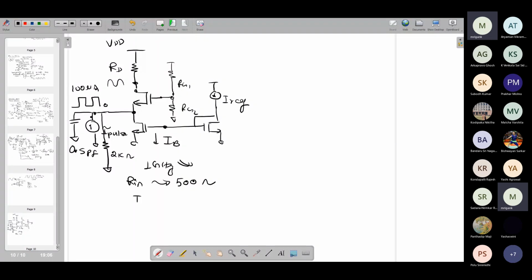Bias current, whatever total bias current in all these circuits. After this, you can use another amplification stage also, and you can limit the gain of this stage. You can use another stage also, which can be either a common source or a common gate. You can have a common source stage at this particular point, depending upon the bias condition that you are providing.